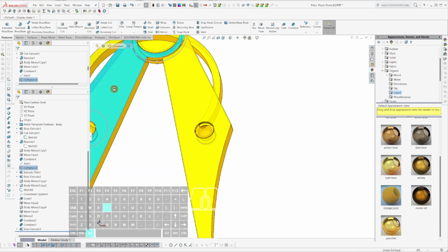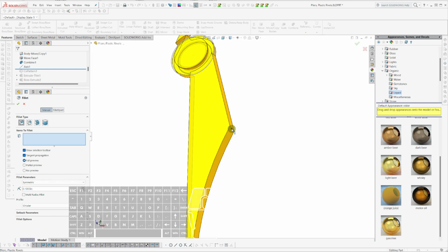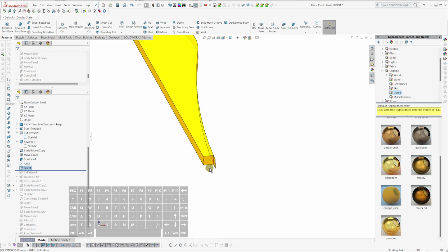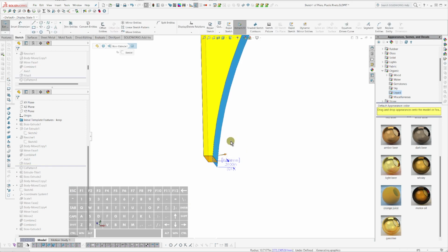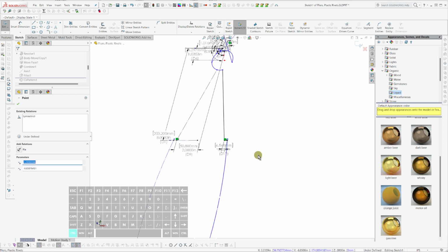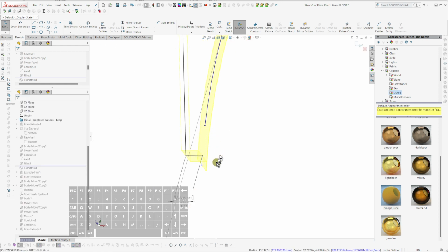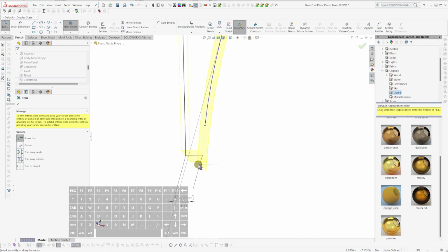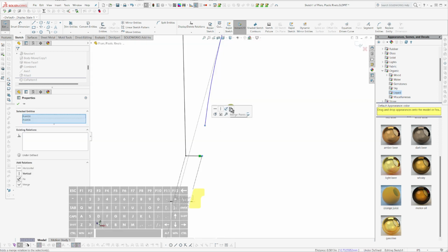And I am going to go back to before this. I'm going to add a fillet here of, I don't know, an inch? Sure. And I'm going to add a fillet here and here. This line gets goofy. Whoa, not how I drew it up. I'm going to trim that back to there. I'm going to trim this, and then I'm going to select that and make that and that coincident.